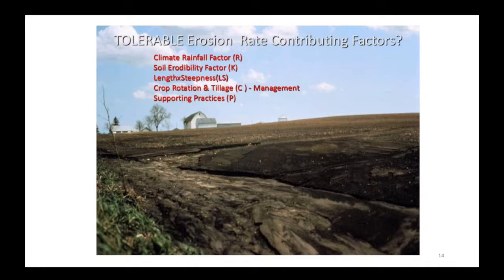What's also embedded in the rainfall factor is what we refer to as 30-minute intensity ratings, which is again embedded in the R factor, meaning that a storm event that has a quarter of an inch or more of rainfall within a 30-minute period helps us understand what we refer to as an erosion index that is assigned within RUSLE2, in the R factor.